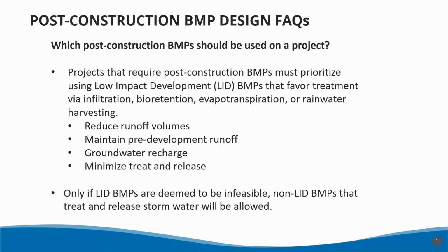They do have a lot of positive benefits, including reducing your runoff volumes, keeping your runoff on site as much as possible, and also maintaining or matching your pre-development runoff hydrology. As you do infiltrate or retain stormwater, it does lead to more groundwater recharge.